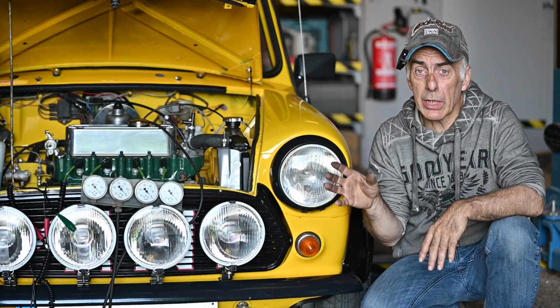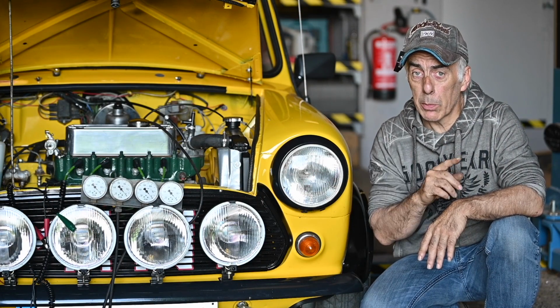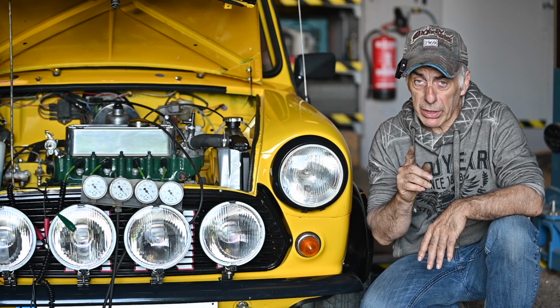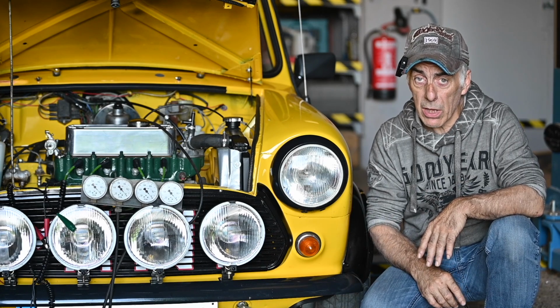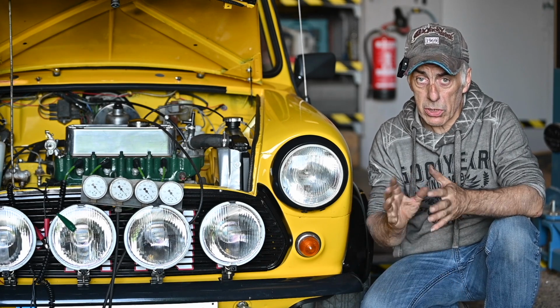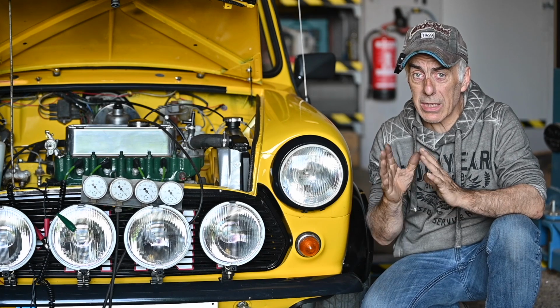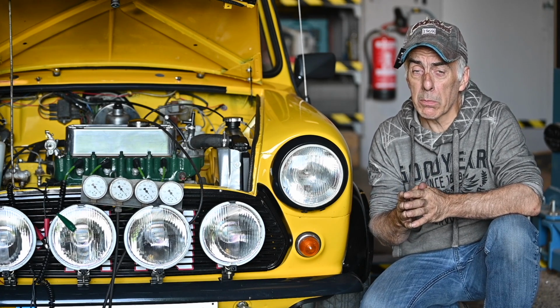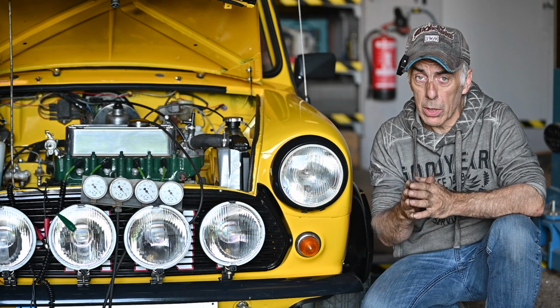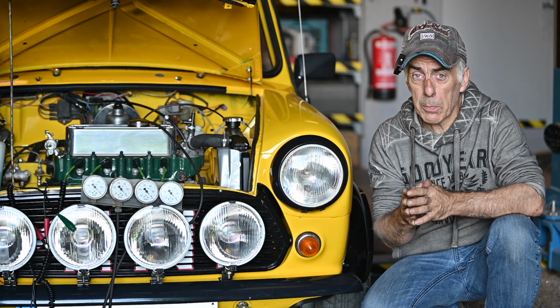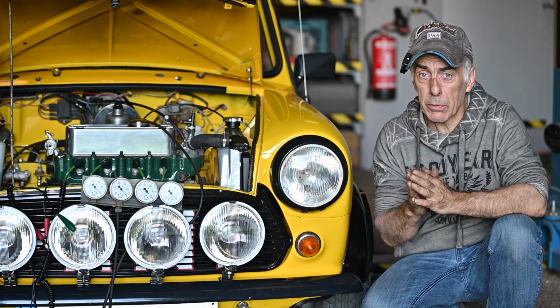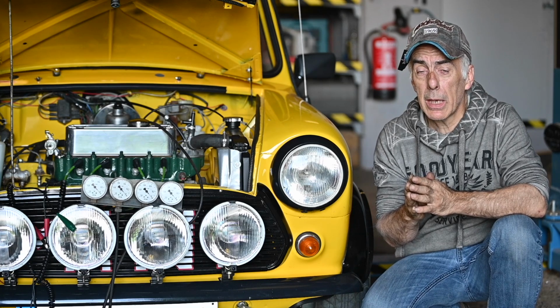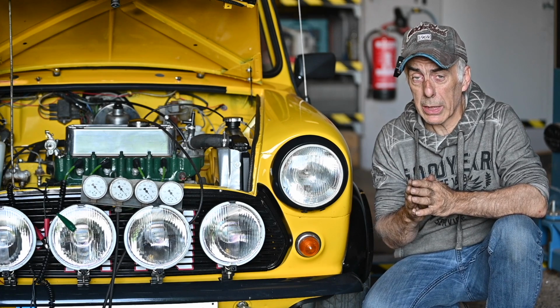Move the engine until it's aligned, and then double check on the front pulley if everything lines up there as well. If it's not, then you can adjust those things. But okay, for now, let's assume that the pointers on your engine block and the marker on your crankshaft pulley are properly set, that they line up to real top dead center, and then we can use a strobe light to look at it.